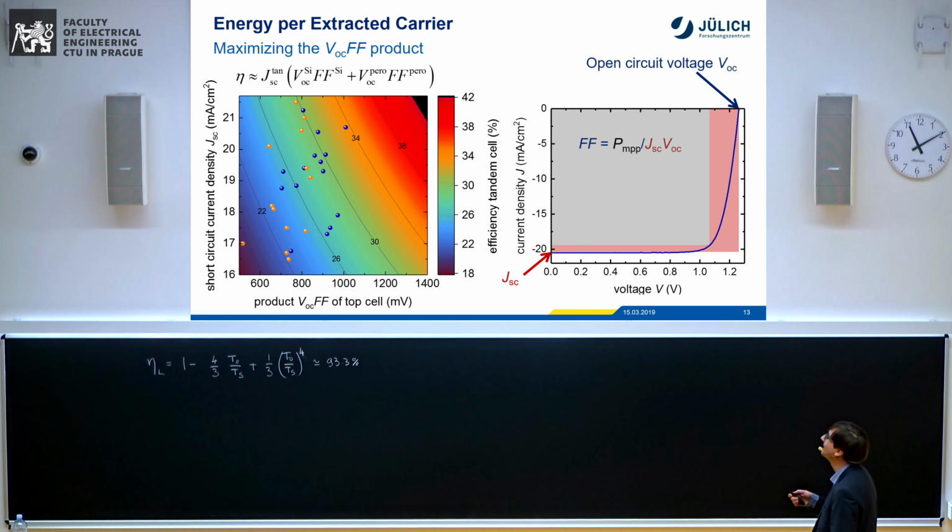And you see, if you could keep the 20.7 or so short circuit current, if you remove the back reflector, the back mirror, and then put it on top of a crystalline silicon solar cell with 26.6% efficiency, you could go towards 34%.